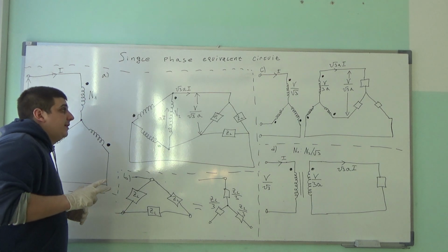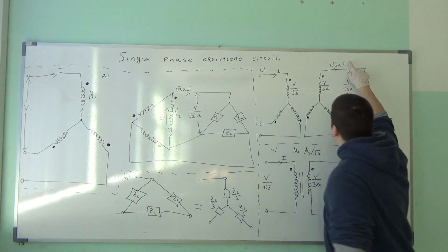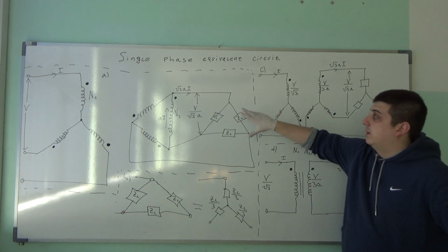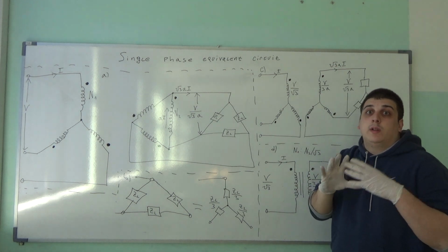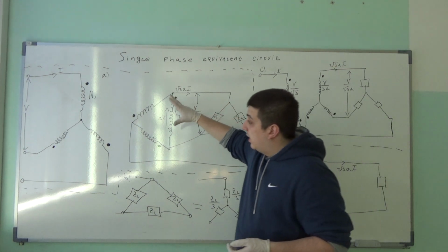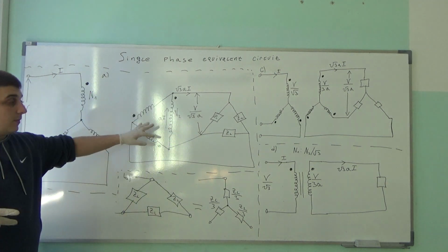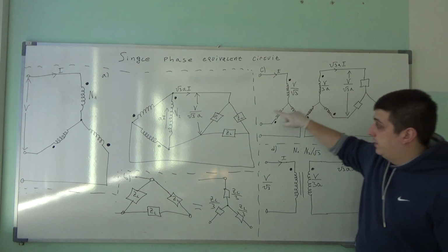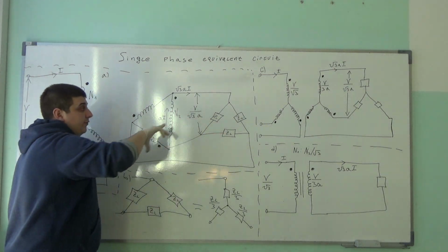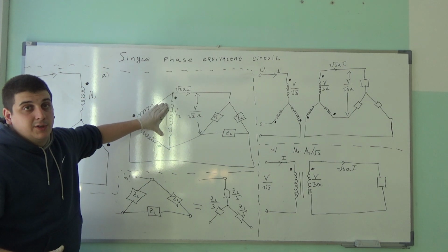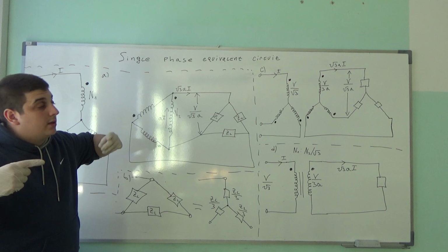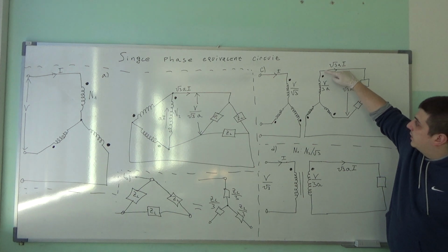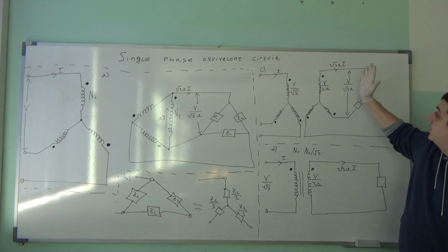So, on the output we want to have the same line current, and we want to have the same line voltage, like here. So what changes if we want to transfer this to a Y configuration? Well, if you want this and this to be the same, look, in the delta configuration the line voltage is the same as the phase voltage, but in Y configuration that is not the case, because phase voltage in a Y configuration from here to here, that's the phase voltage,